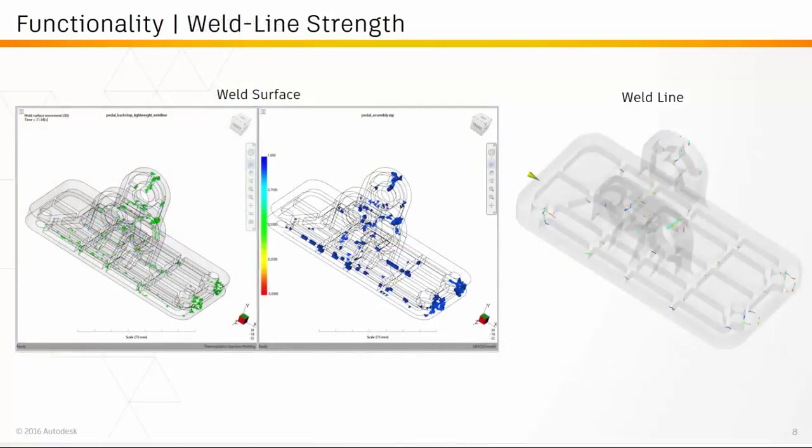We have also added some functionality for weld line strength prediction. Within Helius PFA, we can now map 3D weld surface data from Moldflow to the structural simulation.